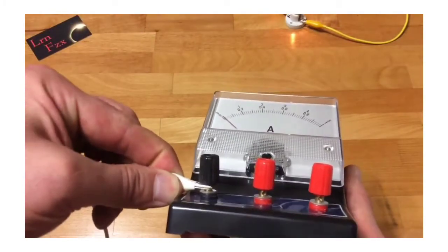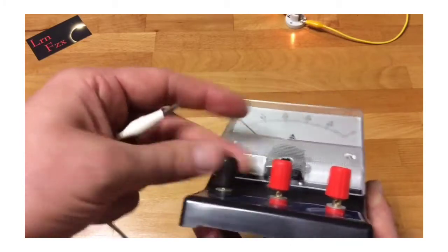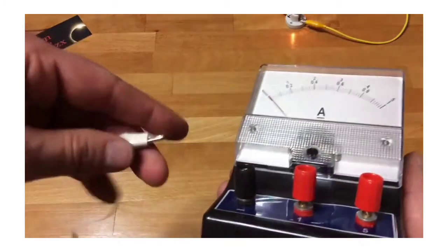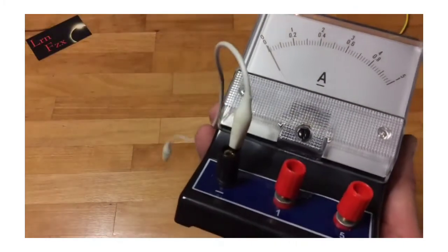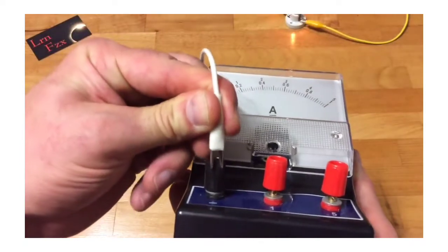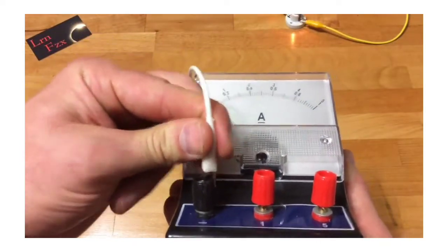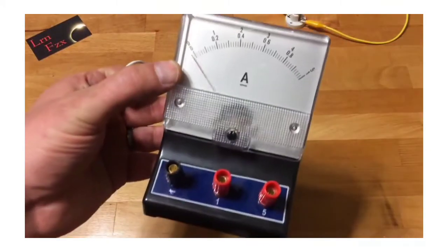Positive, two possibilities for the positive. You can connect either to the side, like that, or if you screw in those little plastic nuts, you can connect to the top. Just make sure you get metal every time you clamp. Two different ranges are represented by the positive 5 amp range or the positive 1 amp range, with the two different connectors in the two different ranges.